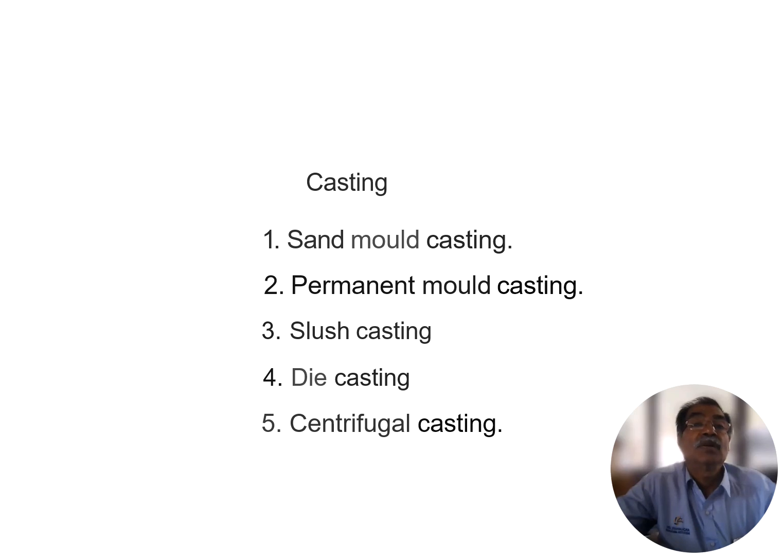They have some advantages. They have a more favorable fine grained structure. The dimensions may be obtained with close tolerances, and holes of up to 6.35 mm diameter may be easily cast with the metal cores. Next is slush casting. It is a special application of permanent mold casting. This method is used for production of hollow castings without use of cores.